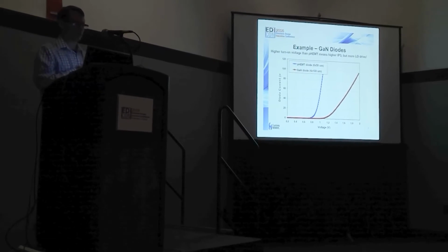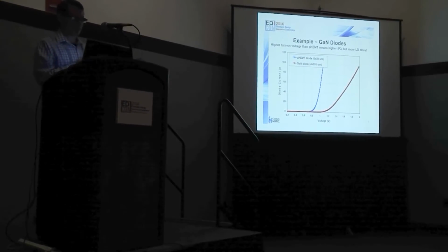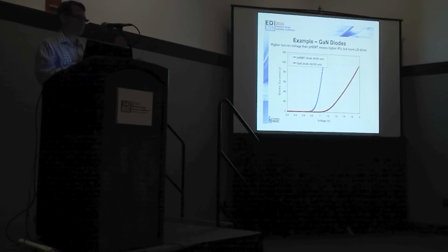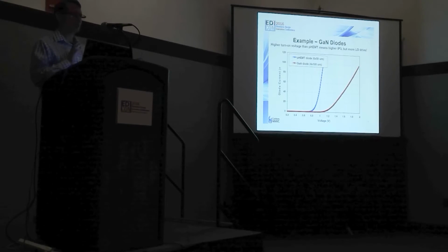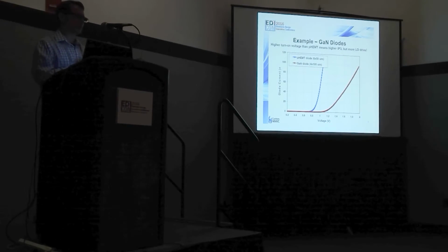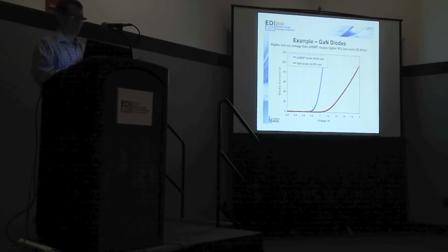This is a 300 micron device that we put through the IV tracer. And what we can see is it has a turn-on voltage of about 0.75, 0.8 volts, where the current really starts going through the diode. And that's fairly typical of most PHEMT processes. You can move that turn-on point a little bit, but you're pretty much around 0.6, 0.7, 0.8 volts.